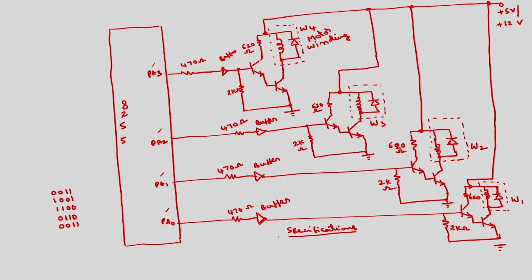Like that you have to repeat the sequence. In between two consecutive sequences, what should the delay be? That depends upon the speed. The specifications are the speed, which depends upon the application, say 12 RPM, revolutions per minute. I want to rotate this, say with number of teeth n equal to 200. The number of teeth is 200.